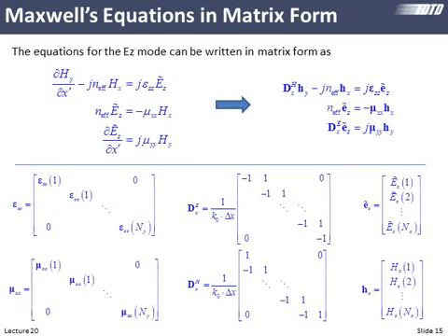So what do these look like, and how are they populated? They look like this. They're banded matrices, and they essentially have two dominant diagonals. And if we take this big matrix, multiply it by h sub y, we would see the derivative. So maybe a bit more to this story, but that is something we cover in glorious detail in the computational electromagnetics class. But I think you have enough of a taste of this that you can appreciate what's happening here and how we can go straight from the analytical equation to our matrix form equation.